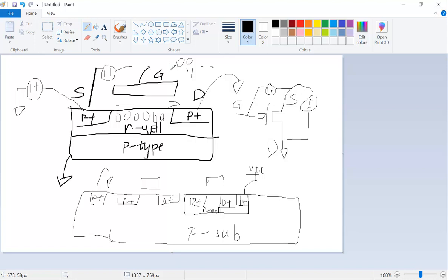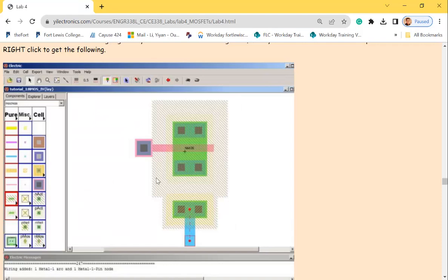You can leave holes at the edges of the chip, so you can make the connections to the metals. And eventually, these top layers of metals will have connections to the very bottom transistors. So this is the very bottom layer of the chip. So for this one, this is the channel. The green color here is the channel.